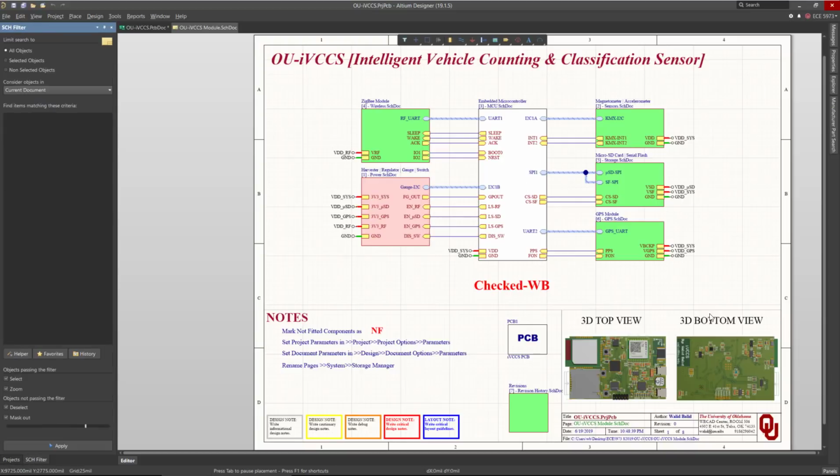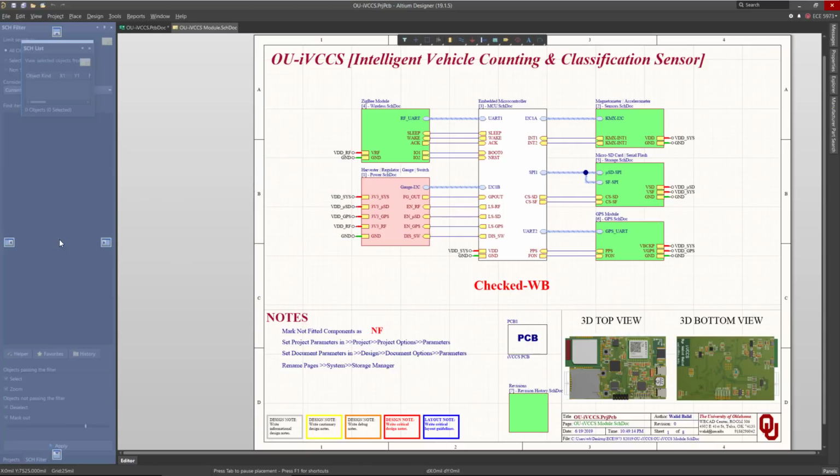So basically, to have this mode, which is a tabbed panel grouping, let's say we have another panel, schematic list. Just drag the source panel over the center of the target panel. You see these arrows on the top, bottom, right, left, and all four corners.